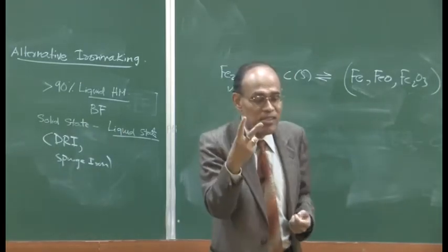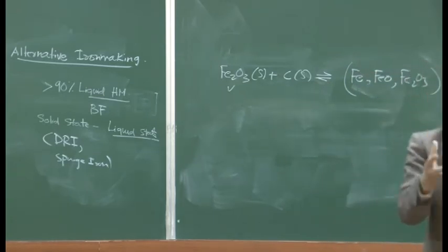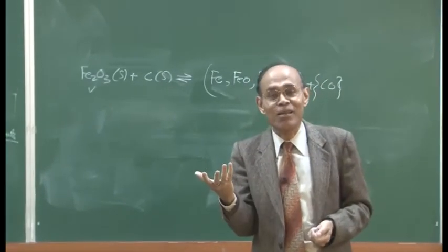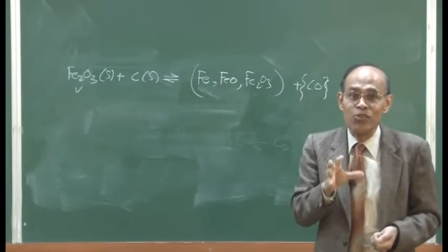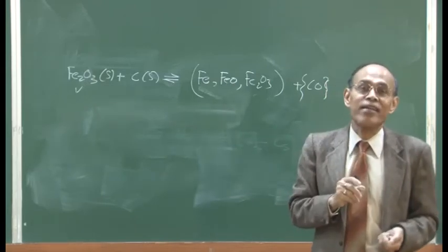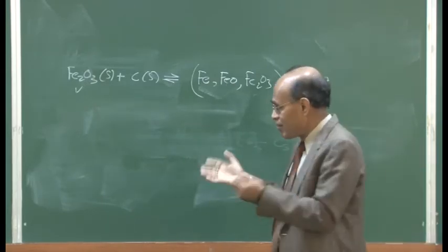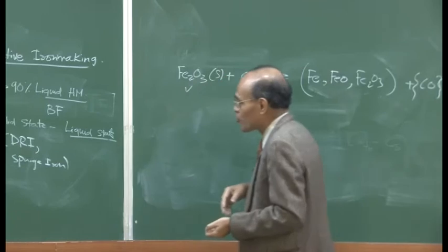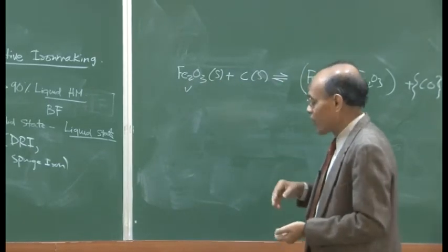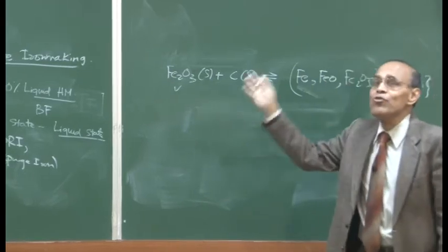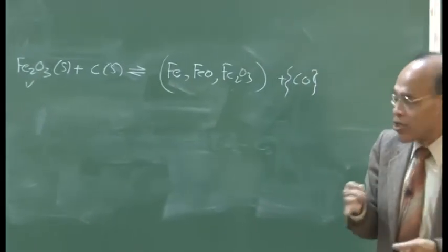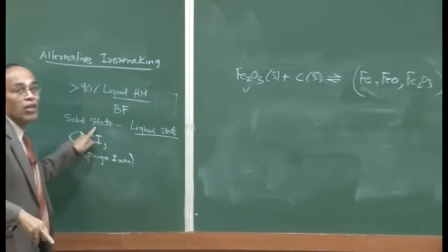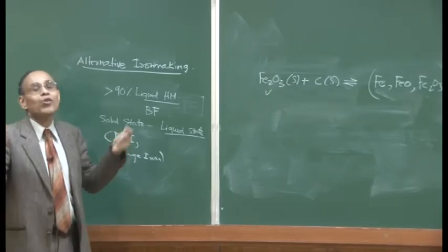So, these are two reasons: coke is decreasing, so we want a cokeless iron making process, and we have no scrap or very little scrap available in the steel plants, so we need coolants. There the DRIs particularly provide us an opportunity to use solid state iron, iron reduced in the solid state, as an effective coolant. Now, there are many routes given this objective, that we want to produce liquid iron using coal and solid iron using coal. There are a host of processes which are available.